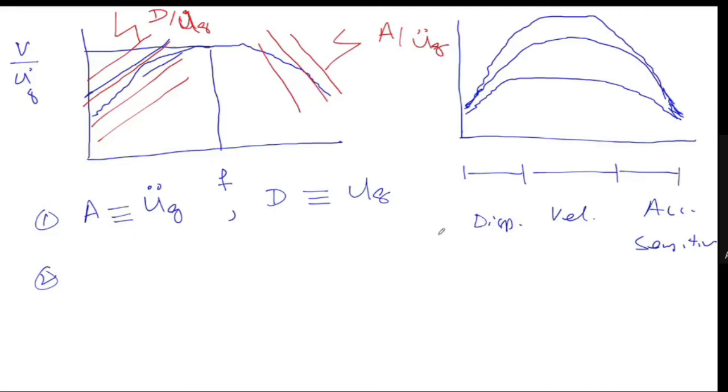Okay. In fact, in these regions, like in here, the response of the system is mostly or closely related to the acceleration. Here, it's closely or mostly governed by the velocity, and this is mostly governed by the displacement. Also, if you look at the spectrum, you will see that these spectra are developed for various damping, and you can see the damping is increasing in this direction. So this is increasing damping.